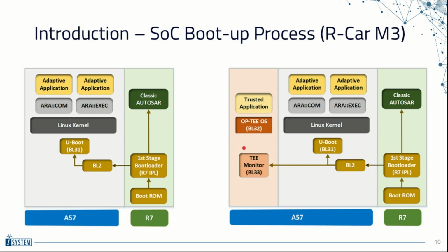And you can see that the bootloader configuration becomes really quite complex. Now, despite this complexity, all of these bootloaders, with the exception of the boot ROM, can be instrumented using STM and traced at the same time. Later on in the example, we will see how winIDEA shows us a nice overview in the timeline of what is going on.